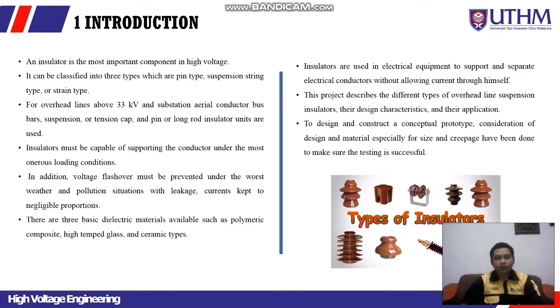In addition, voltage flashover must be prevented under the worst weather and pollution situations, with leakage currents kept to negligible proportions. There are three basic dielectric materials available, such as polymeric composite, high-tempered glass, and ceramic types.